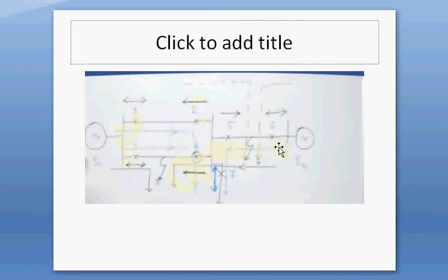Here we have got relay 5 and relay 6. Under normal working condition, or under normal operation, the direction of current from relay 5 and relay 6 is from right to left. Fine. Now let us assume there is a fault in between relay 5 and relay 6. Now the current from relay 6 is still in the same direction as it was before the occurrence of the fault. So the relay at position 6 is a non-directional relay. Fine. And let us observe the current at relay 5. Now let us follow my cursor position.